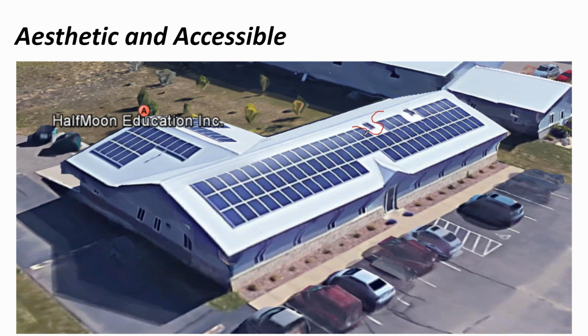What is much more likely, because that solar installer is making that attachment, and we're assuming they're good at their job, is that it's a brand new attachment. Generally what leaks is the pre-existing stuff on the roof, because a roof is not designed to be a job site. When you get a team of workers tromping around on this rooftop around existing penetrations, that can be bad for the roof.